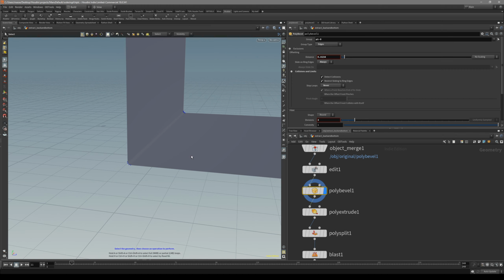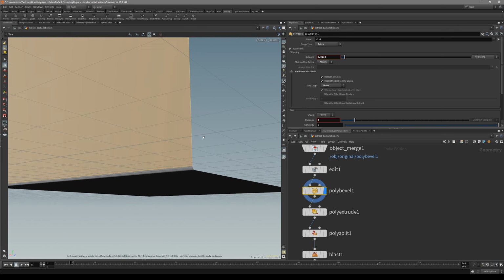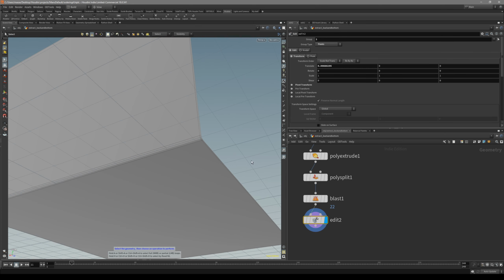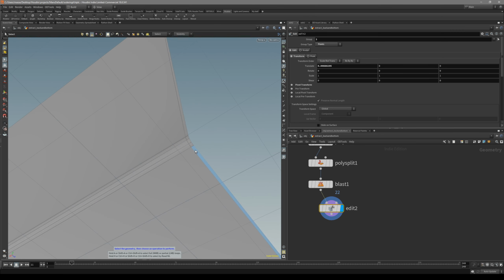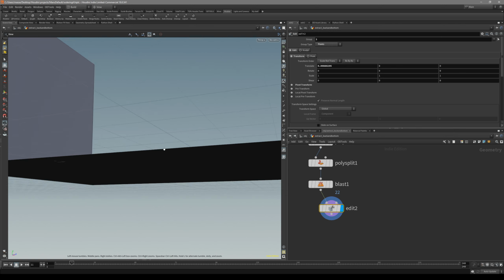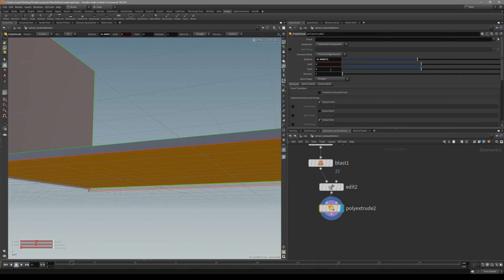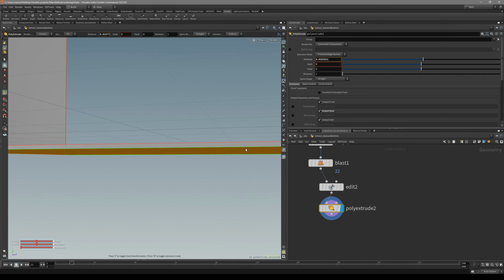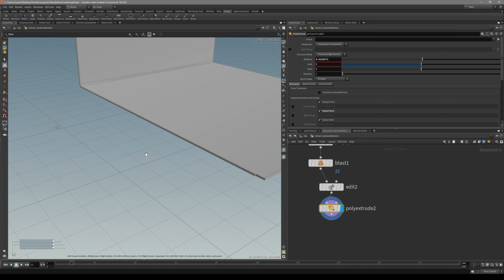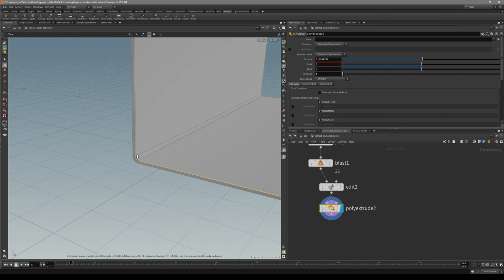Now let's go back to this object. So first of all, what you can do is start extruding it. So let's go back to the very edit that we just made. So we did some extrusion inwards. Now actually let's give the geometry some volume. So let's just select everything and just extrude. Let's extrude outward so that our normals are not all weird like that. And you can see we're left with this kind of a lip that we can extrude inwards.